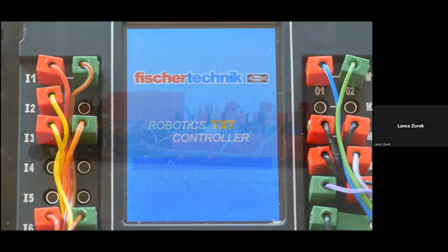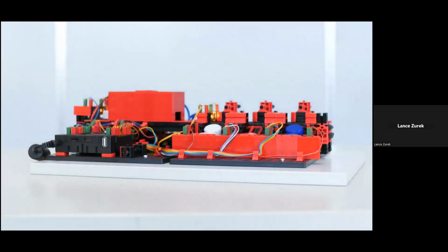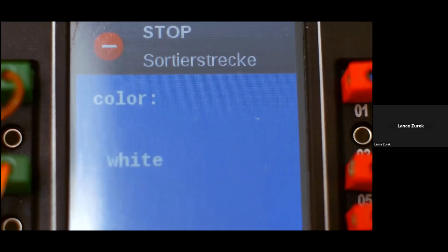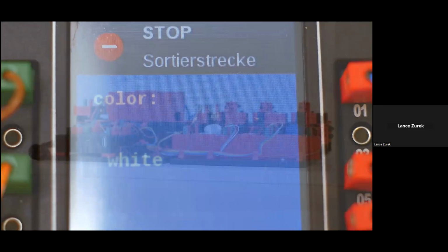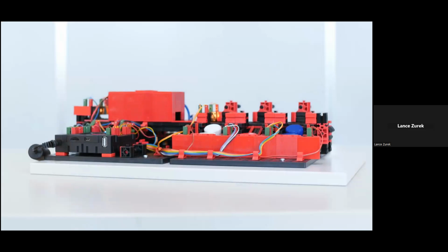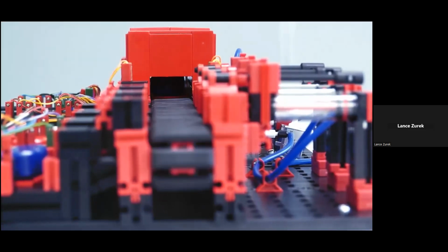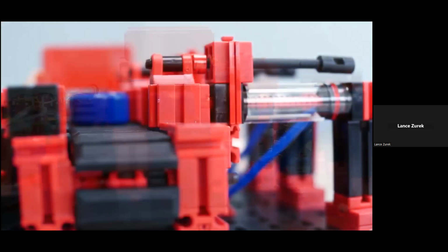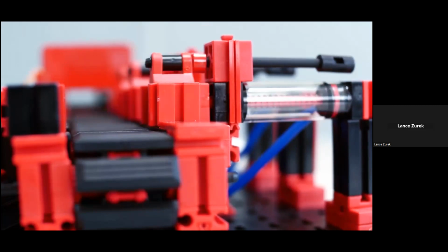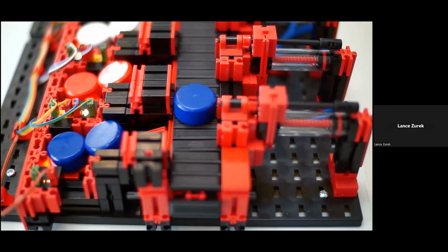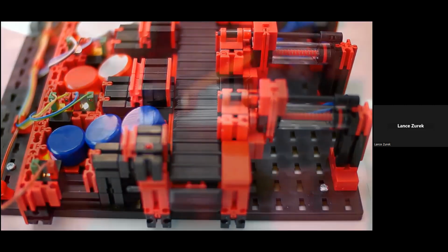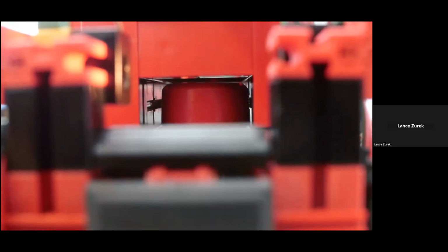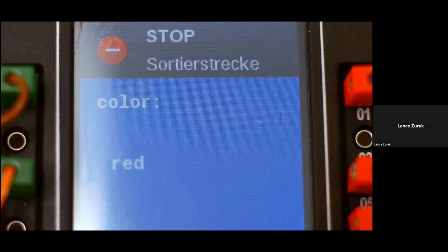The dimensions for this model are approximately 20 by 14 by 12 inches, and it has a weight of just about 10 pounds. Now, as with the models we've looked at before, the standard 24-volt version has a relay board for motor polarity reversal, and both a multi-pin connector, again 34 pins, with a grid of 2.54 millimeters, as well as additional PCB terminals with push-in connections for all inputs and outputs. And again, you will need to provide the PLC and the programming.